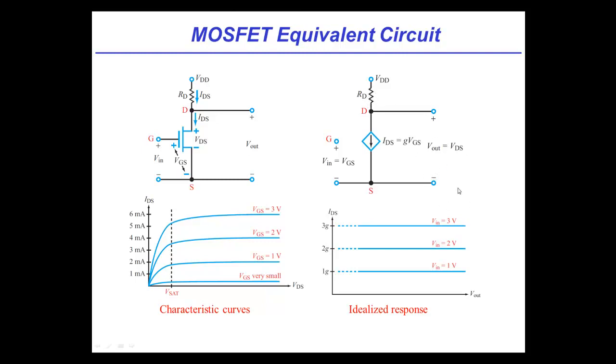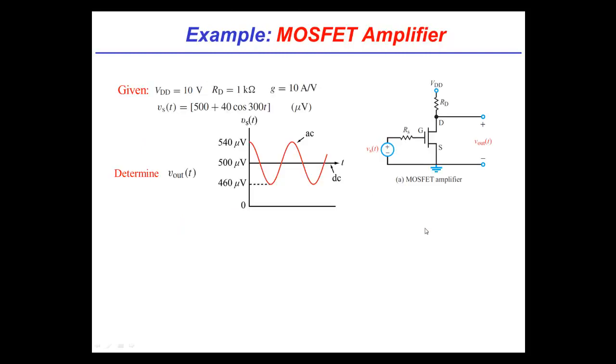So that's a neat thing we'll come back to in a minute. So if I understand that correctly, all you just told me is that the output voltage is just going to be VDD minus the voltage drop across here, which is just the current through here. Yeah, exactly. Times the resistance. Times the resistance. Okay. So let's do an example.